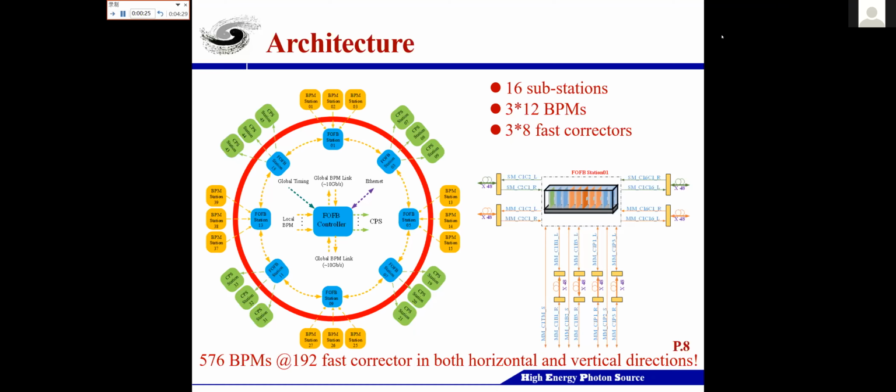For performance tuning and additional flexibility when adding or removing BPMs or fast corrector power supplies or loading new matrices, we use the on-board Ethernet controller, designed as a hardware TCP/IP protocol, to connect to the substation by using SPI.